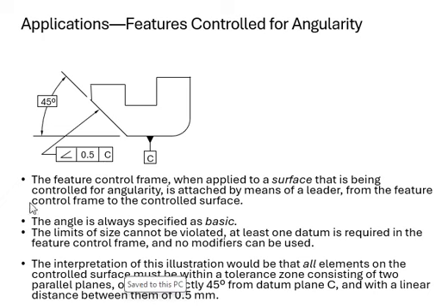Okay, so when you look at this example, of course your angle is oriented 45 degrees from your datum plane, which is your C right here, and of course the distance between them is going to be 0.5 millimeter. Again, some people have an issue understanding where this 0.5 millimeter is. It means the parallel planes, right? So that parallel planes is the tolerance zone right here.